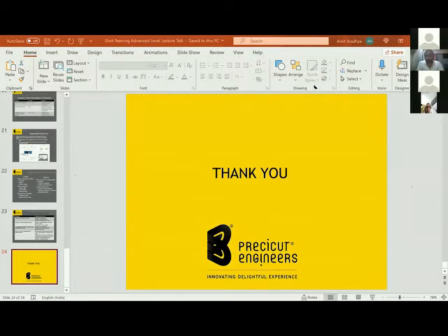What a design engineer is going to do is firstly shot peen a few components, measure the stresses, and test the components for their fatigue failure. At the point where they have got good results, or the results that they want, they'll check what the corresponding arc height is. To this arc height, you add some safety factor and then mention that arc height on your drawings. So this is the first part.